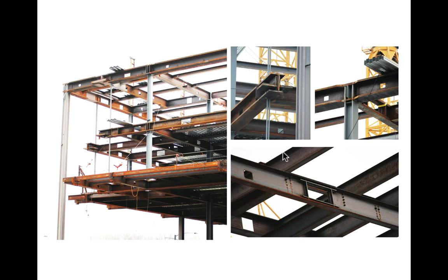If you look at steel construction, you can see this principle at work. Whenever we have penetrations that we need to put through a web for mechanical reasons or otherwise, our engineer is going to be fine with that if they're in the web, and they're going to be happier if those penetrations are closer to the center of the beam. So here you can see this is a set of steel beams that's got a lot of penetrations in it, a lot of ductwork going through those beams, and the engineer is fine with it because the web is not the part that's doing the work in bending. It's the flanges, and so long as those penetrations are close to the center of the web, it's not really affecting the strength of the beam. It's affecting the strength of the beam in shear, of course, but in bending, those penetrations aren't hindering it very much. It's mostly the flanges that are doing the actual work.